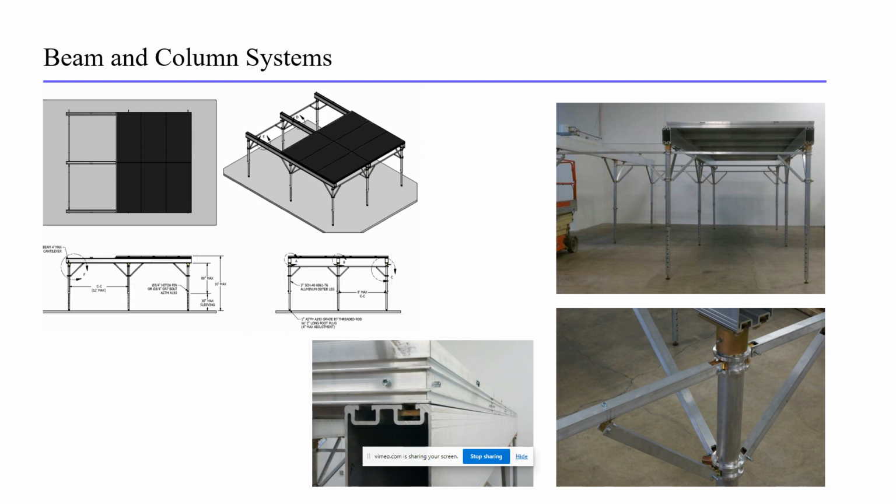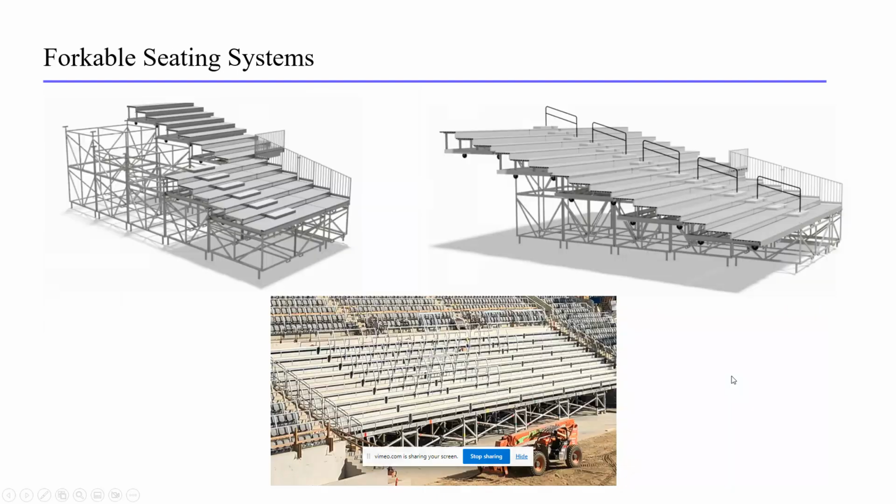It's not off-the-shelf engineering. Highly customizable, used for demountable, semi-permanent, and even permanent solutions. You'll find this style of support typically around a vomitory area in an arena or in a stage trap of a theater, where you need a lot of open space underneath, where you have people or equipment passing underneath or using that space.